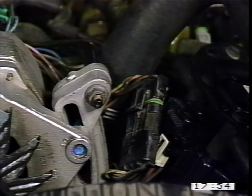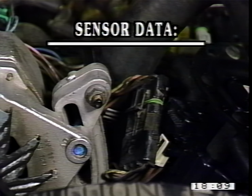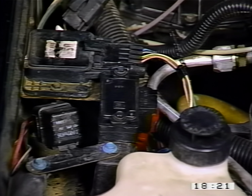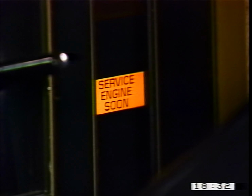How much the EST return signal is advanced or retarded depends on three things: the calibration of the ECM, the permanent factory data stored in the PROM, and information coming in from other primary inputs, including manifold absolute pressure, throttle position, coolant temperature, and oxygen sensors. MAP sensor data is used by the ECM to monitor engine vacuum and to adjust timing and fuel. It takes the place of the old vacuum advance and power valve. MAP sensor circuit problems are identified with the code 32.